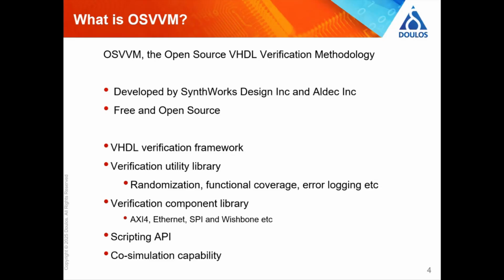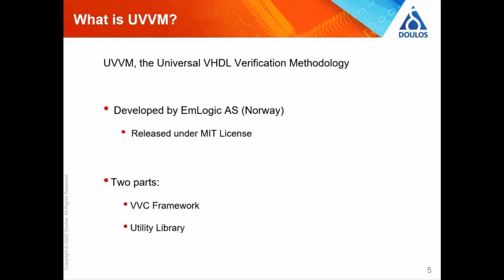Originally it was focused mostly on randomization and coverage. And since its original inception, it's grown to be more of a whole verification framework if you want to use it. As such, we've got utilities for doing randomization, coverage, error logging, we've got component libraries, scriptability, this sort of thing. Which is actually very similar to what we have in UVVM, the Universal VHDL Verification Methodology, developed by Logic AS in Norway, and again, open source, released under the MIT license.